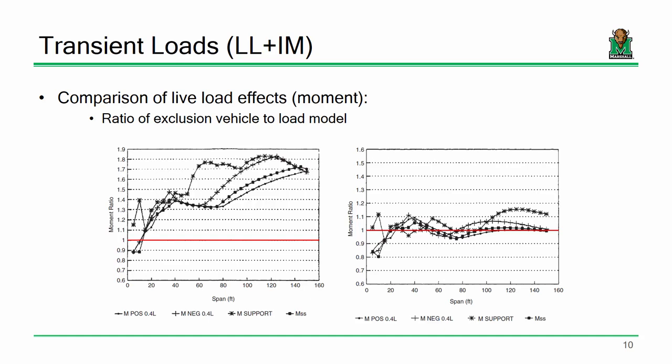That's bad, okay? Because over time, the loads that those highway bridges were seeing were heavier, okay? So when we started to recalibrate the load model, we said, well, is there a way that we can incorporate this? And we said, well, how about this? Instead of doing the truck or the lane, why don't we do the truck and the lane? And that's basically the long and short of what you're getting on the right. It's not perfect, but it's a whole heck of a lot better than we had before. Okay? All right. Make sense? All right. So this is just sort of a justification for what we're doing and why we're doing it.